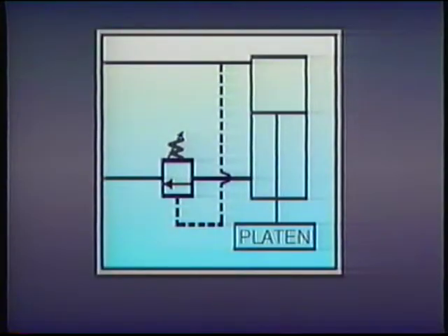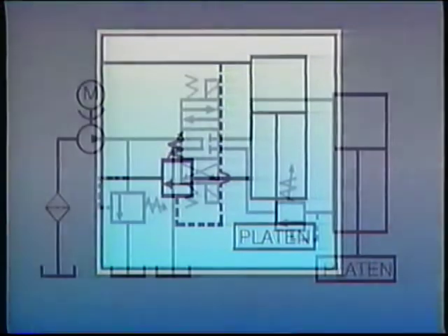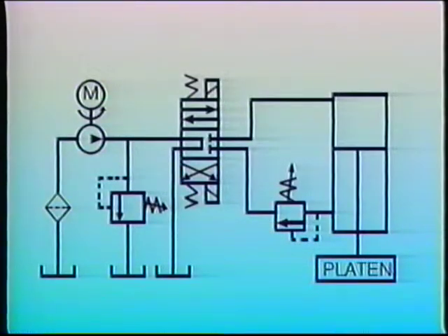For example, in this hydraulic press circuit, a pilot line senses pressure upstream of the cylinder. This allows us to maximize the force which can be applied as the platen presses through the workpiece. Let's take a simplified circuit and see how it works by assigning some values to the circuit we saw earlier.